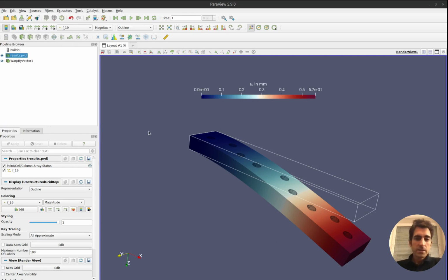So what we have seen is now a combination of FreeCAD and FEniCS. Do we really have to use it? No, I mean, you can also use Calculix, right? So there are different options for elastostatics. For the simple case that we want to do, both of them are equivalent. I'm not gonna say one is way better than the other one. But if you want to do a generalization, and if you want to have the full control and knowledge of what's going on behind, FEniCS has some advantages.